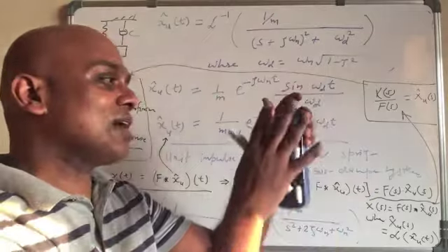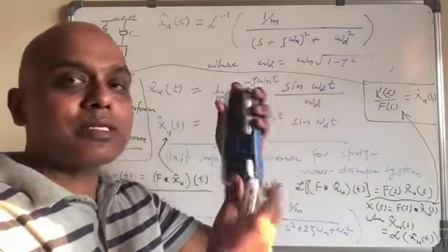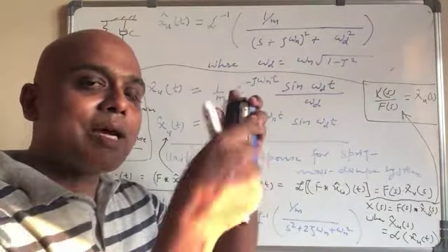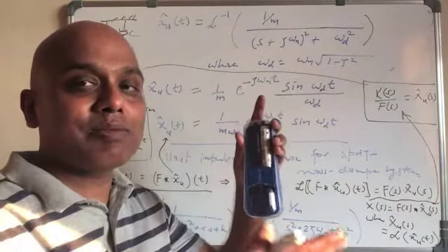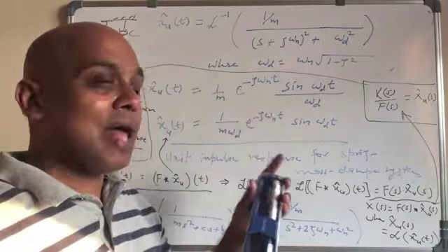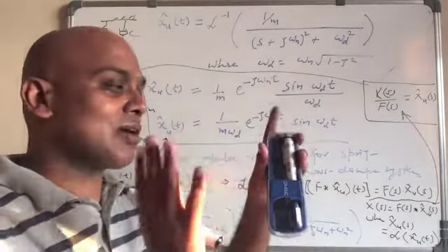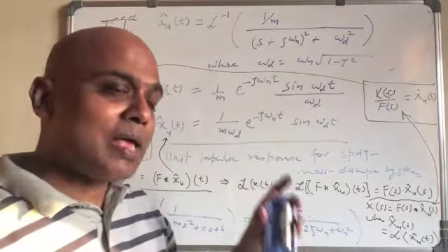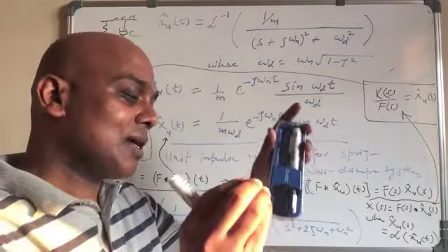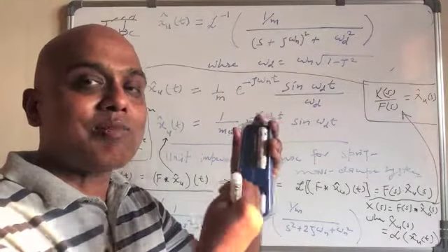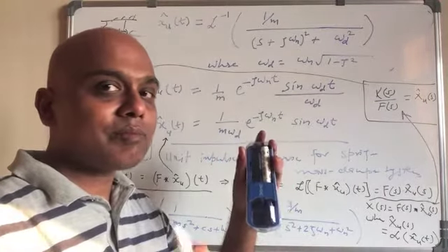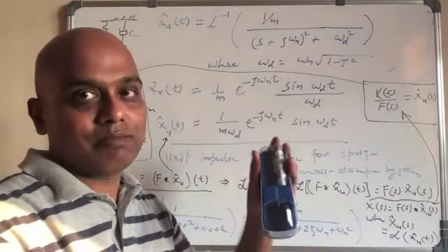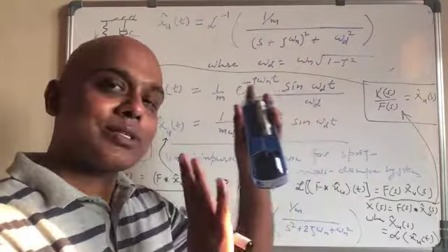We find out the displacement, I record the displacement, and I do the Laplace transform of that displacement. Then I have the transfer function of this system ready, but I have to divide it by the intensity of the force, because the impulse had to be unit. So divide by the actual impulse, and we get the transfer function for this system.